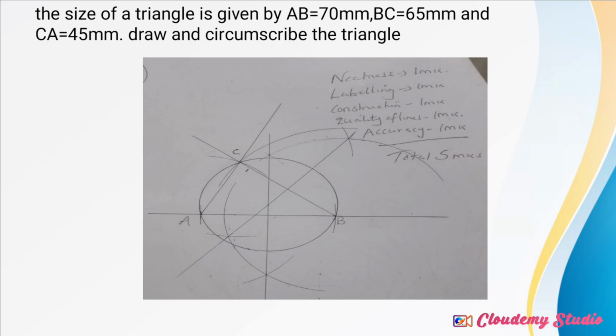So the first step you need to know is to construct the triangle, and here you're just using a pair of compasses and a ruler to construct it, because the question was asking you to construct. So we have to see some arcs to show that you did construct the triangle. First, draw a horizontal line, mark a starting point as point A, measure the correct distance from point A to point B, make an arc, that is your second mark, and label it as point B.